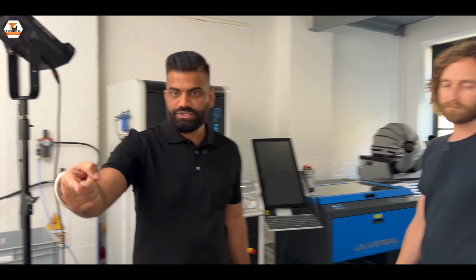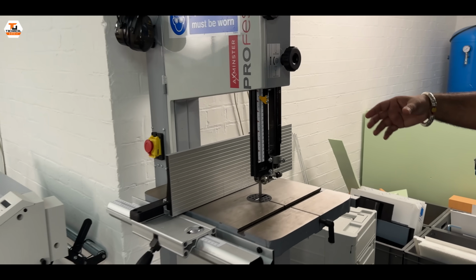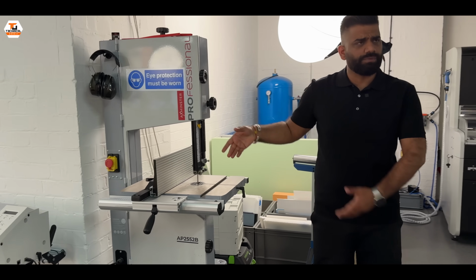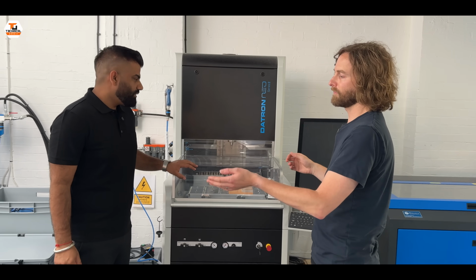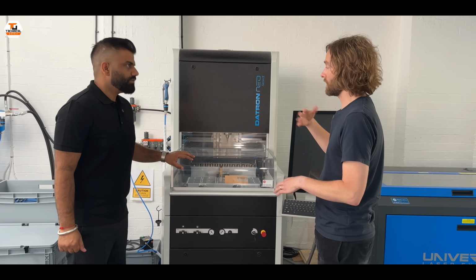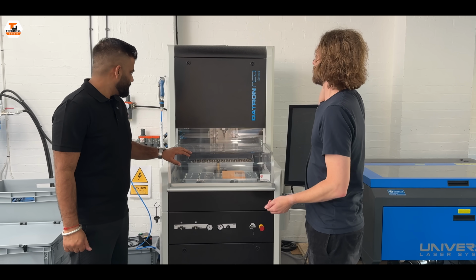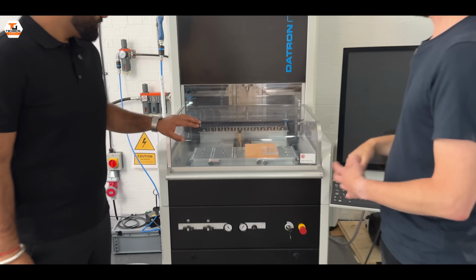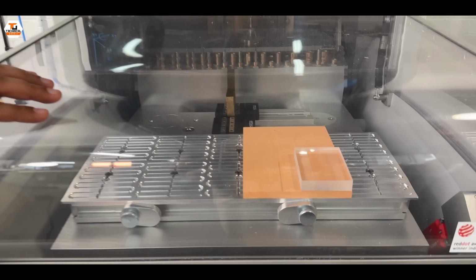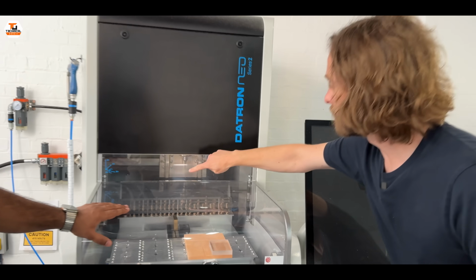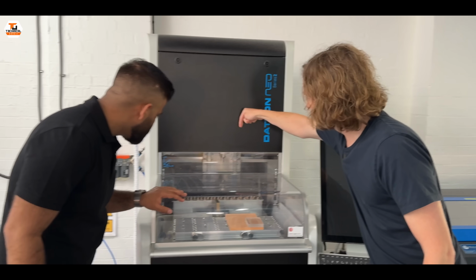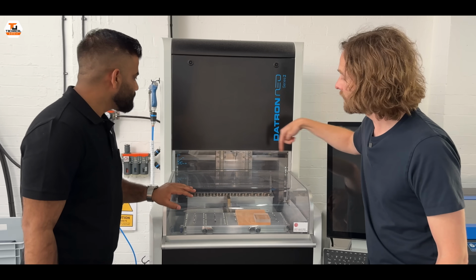We can do basic cutting out on the machine over here. This is just a bandsaw, and you can simply cut the foam for basic shapes. This is a CNC machine. With this you can go from foam up to steel, and aluminium in hardness. You build a model on CAD and put a block on here, and all of these along the back are cutters. The machine head comes down, picks a cutter up, and cuts out that shape.